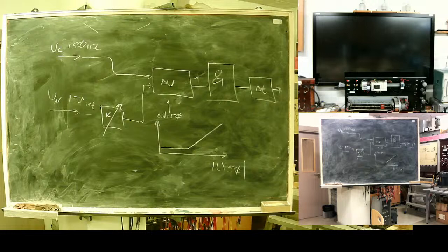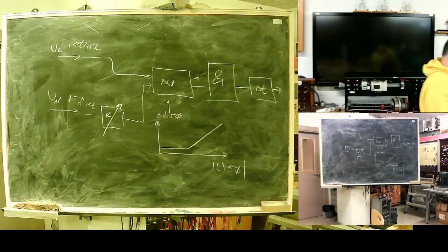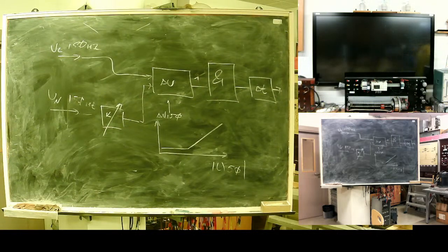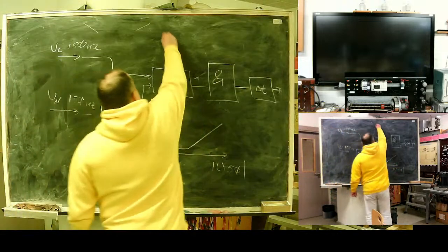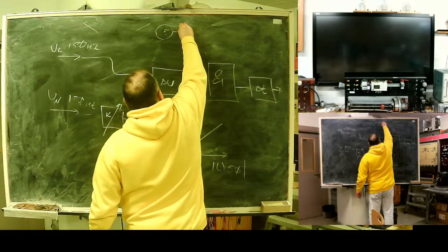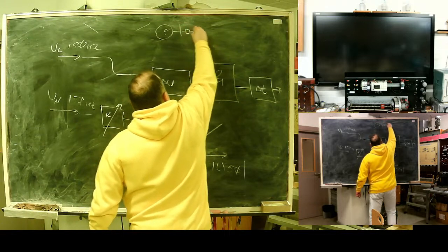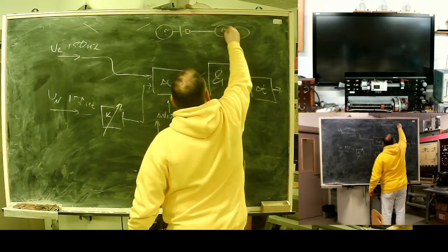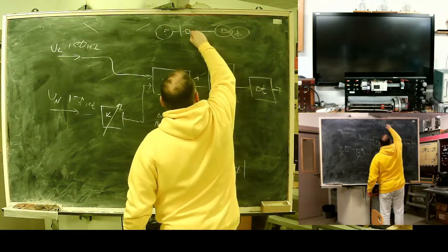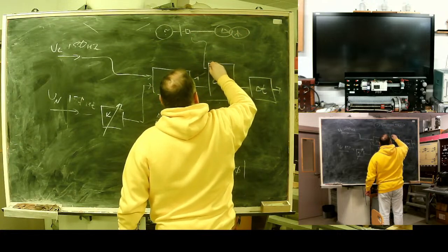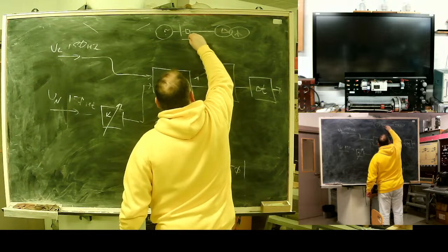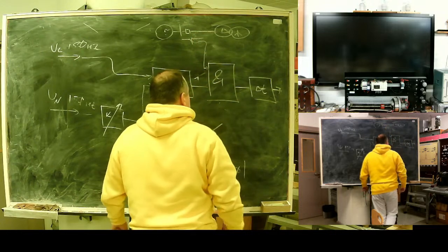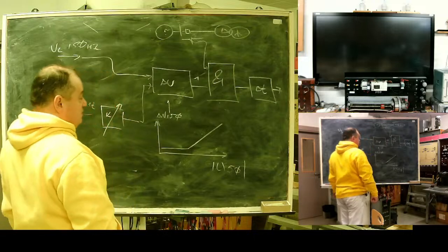If we balance our protection when the generator is connected to the network, this balance will be disrupted at the moment the generator is disconnected from the network. So first, if there is a switch between the generator and block transformer, the disconnected state of the switch should disable protection.